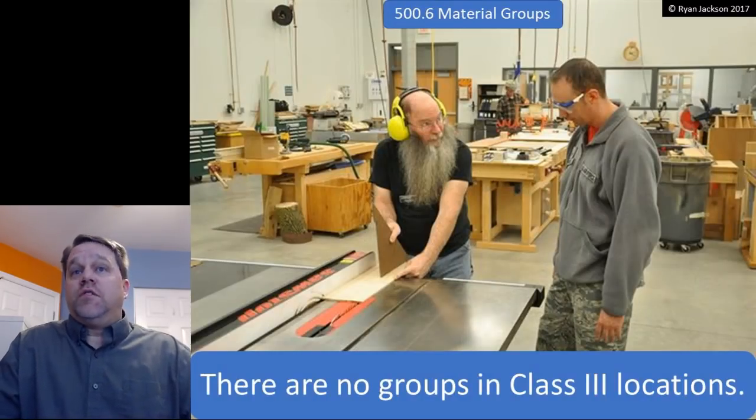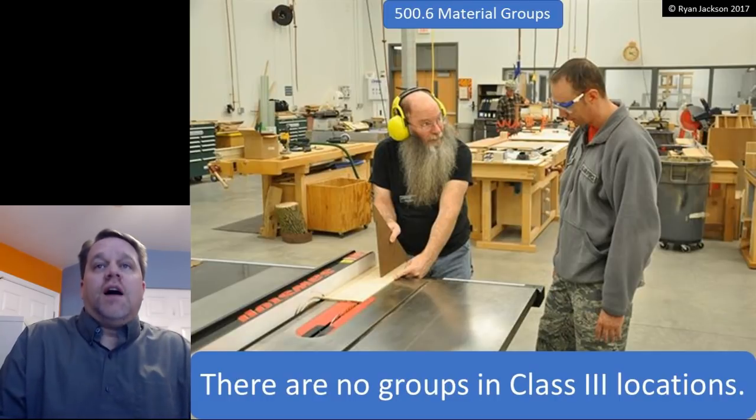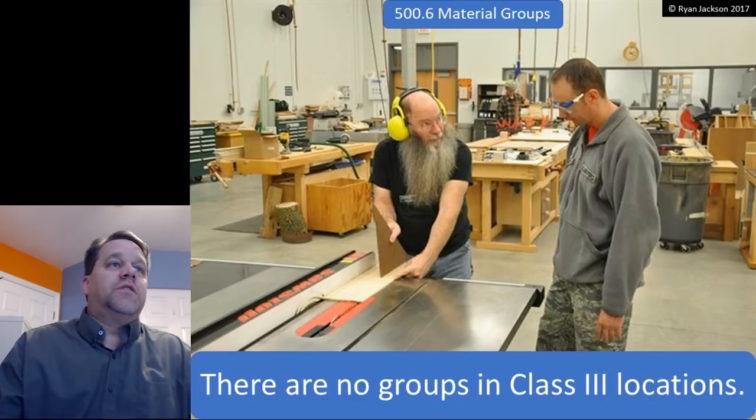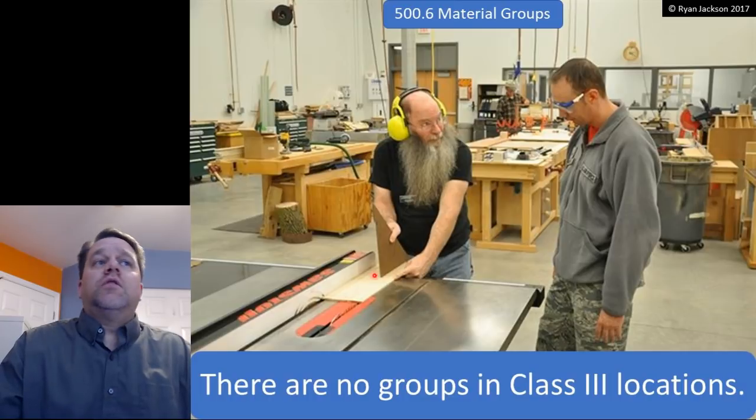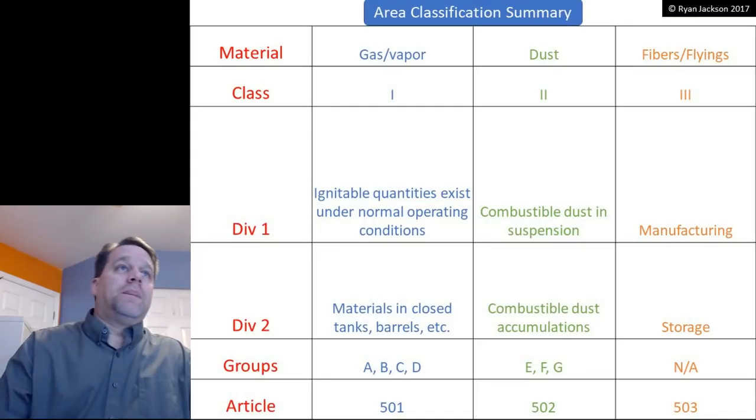Lastly, when it comes to material groups, it's worth pointing out that there are no groups in Class 3 locations. So around the table saw here, if this is deemed a Class 3 location, I don't need to concern myself with group ratings because there are no groups in a Class 3 location. So let's quickly summarize.